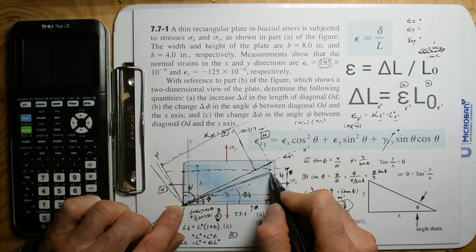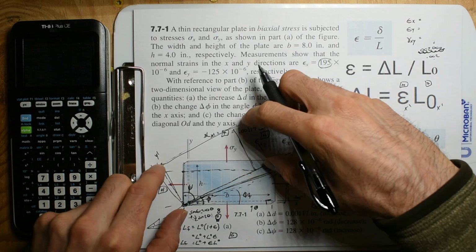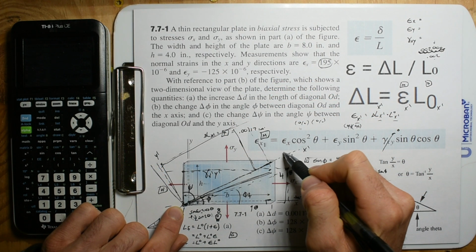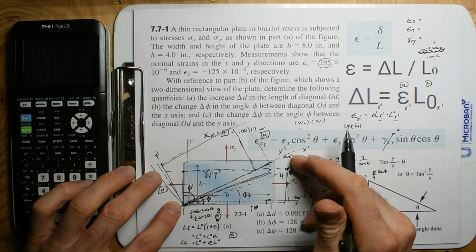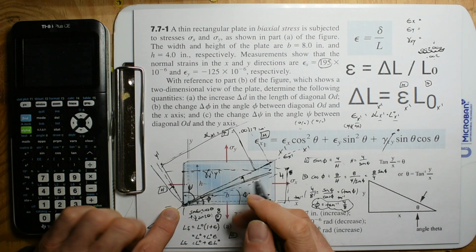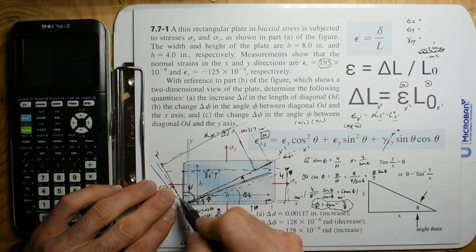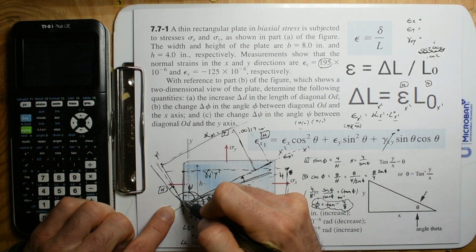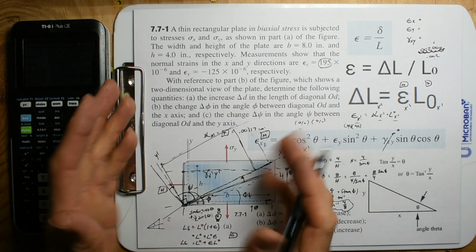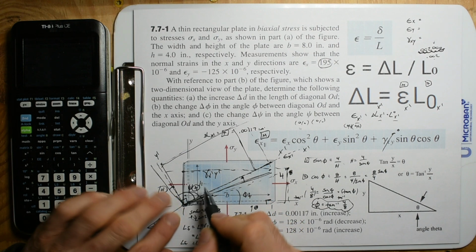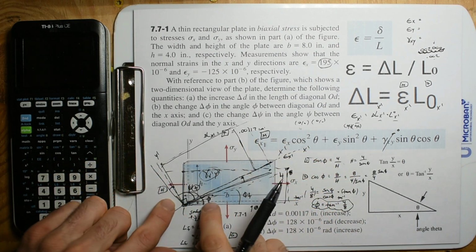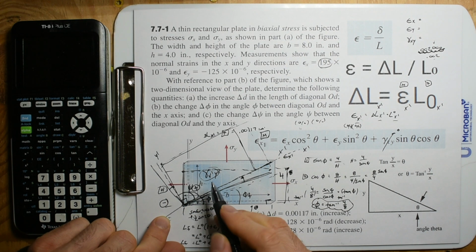So it's only going to be, and if I did rotate this up, and I found the strain in the x1, y1 plane, this is x prime, y prime, that strain is going to give me this angle change and this angle change together. And basically it's going to give me this reduction of angle. It used to be 90, and now it's either reduced or it's going to be, and the reduced angle is associated with positive shear strain. And if the angle widens, that's associated with negative shear strain.